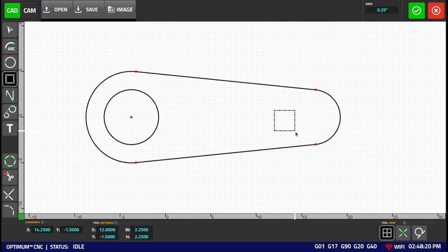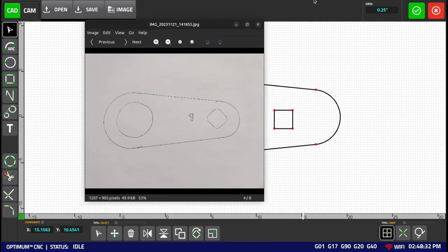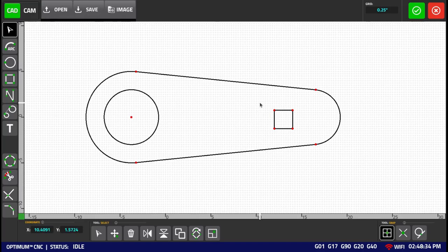So first of all, of course, what you can simply do is create some kind of a rectangle, perhaps a rectangle of a size of maybe, let's say, 2 by 2. Let's say we then think that it's actually a little smaller than we'd like, and we'd like to scale it up. Well, we'll select it, go into our scaling functionality here, enter the scaling factor, let's say maybe 1.2 perhaps, and scale it up.